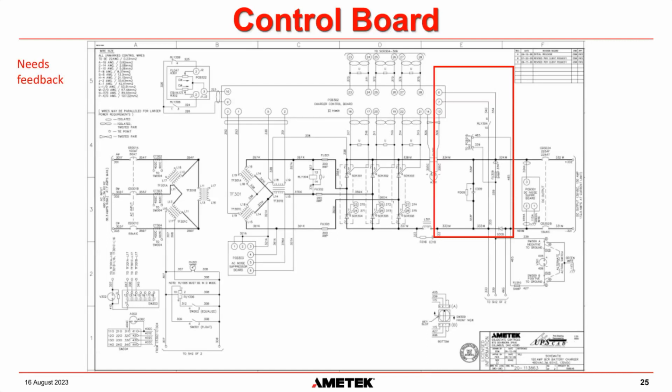Or there is also a backup on our charger control board. It's called the high voltage clamp. And if it sees the voltage going above 145 volts DC, it will actually turn the charger's firing signals off because it knows it shouldn't be up at that level.